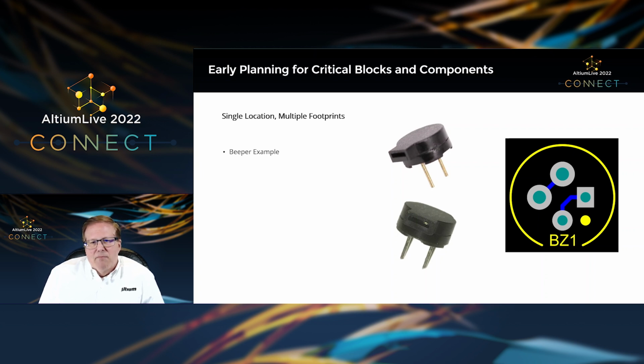So we just put this on our board. This wasn't a variant or anything. It was just a footprint. So at assembly time, we were able to accommodate either one. It turned out the pin spacing was identical. The performance was identical. It's just the orientation of the pin wasn't. So that's how we mitigated that. And there are situations today where this concept might be useful.